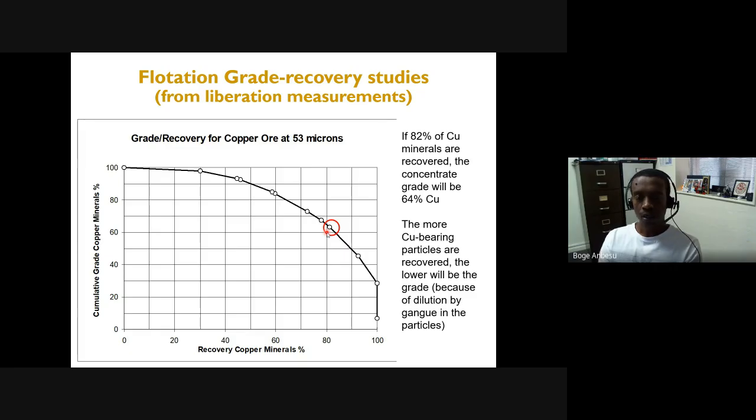Okay. So we'll talk about flotation in particular in the second semester, or whatever semester you are in. But for example, typically in flotation, we have a number of stages. We do a roughing stage, we do a scavenging stage, and we do a cleaning stage. All of these have different priorities. For example, in the roughing stage, all we do is try to maximize recovery.